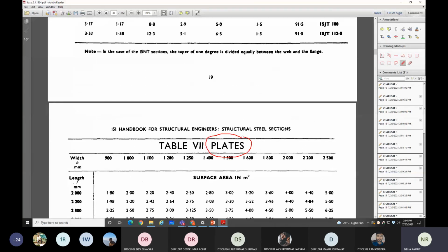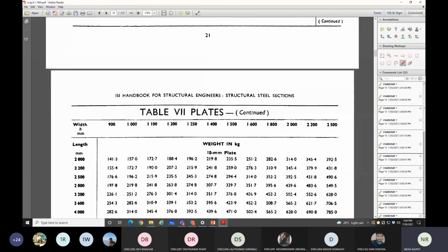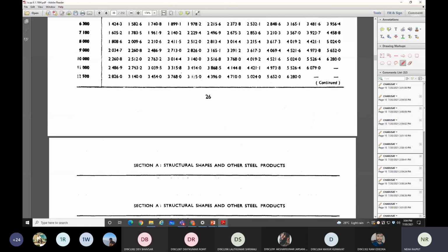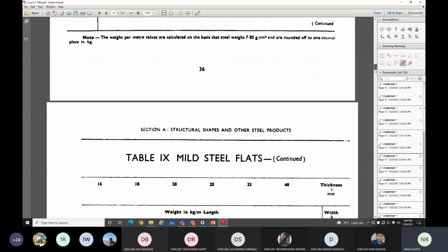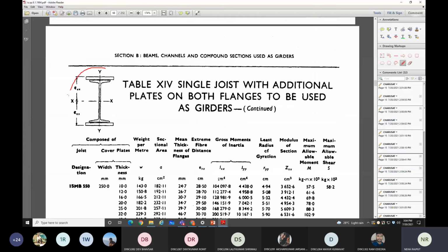अगर आप I beam के ऊपर plates डालते हो तो plate का जो भी dimension चाहिए you will get from this table. Likewise, this is SP6 or you can use steel table also, and you can get the property of steel section that you are using for the design purpose. Different भी है, यहाँ पे देखो I section with joints, plates, additional plate. तो ये सबका प्रॉपर्टी है। Depending on the choice of section selection you can use this SP6 in any of the chapters, right?